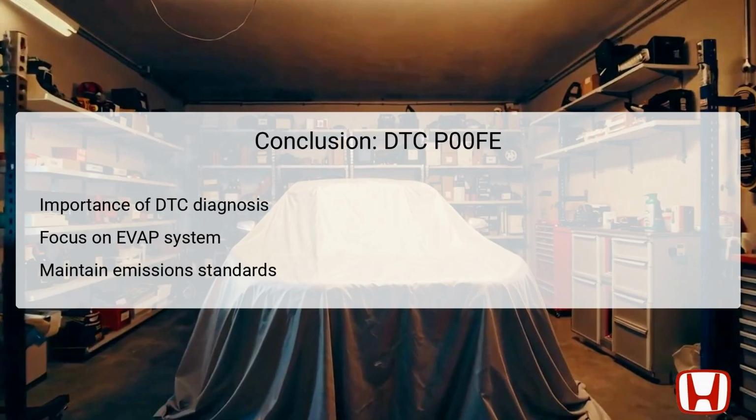In summary, understanding and addressing DTC P00FE is critical for effective vehicle maintenance and compliance with emission standards. The diagnostic process emphasizes the need for clear insights into the function and integrity of the EVAP system, including crucial components like the EVAP canister, ELCM system, and the EVAP leak check module.